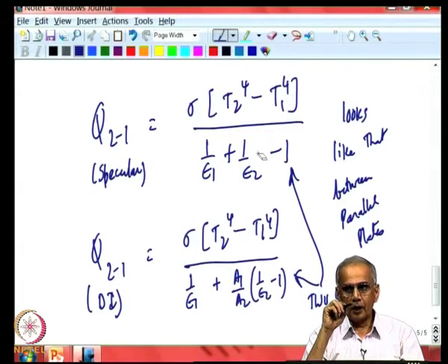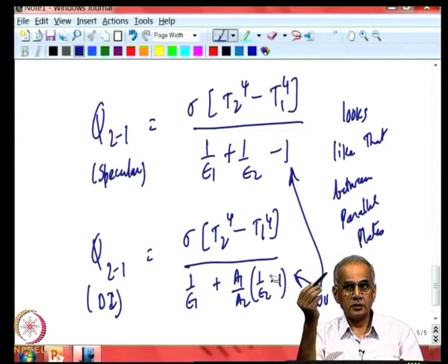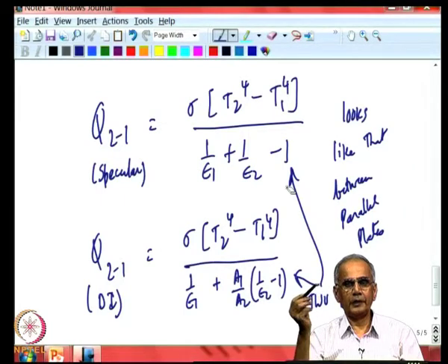If the outer cylinder or sphere is a specular reflector, then the result is very different from if the outer cylinder was a diffuse reflector. If you have a large diffuse reflector, the second term drops out. If you have a large specular reflector, the second term is, the outer cylinder is still important. Okay. Let me give an example.